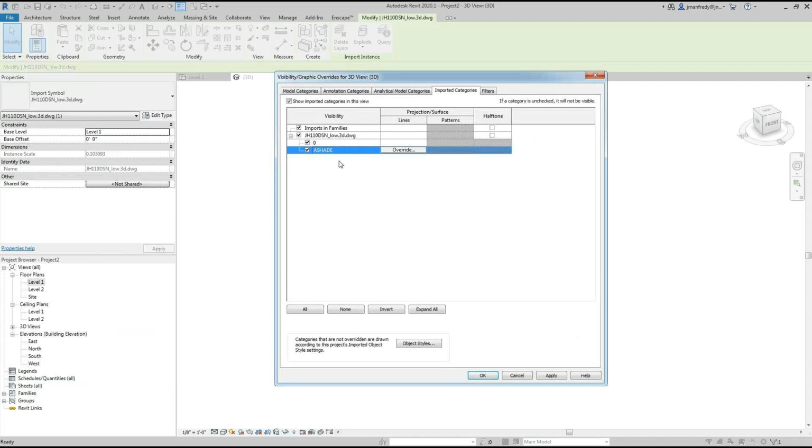These 2 happen to be AutoCAD layers that are brought in by default. In an ideal world, you want an AutoCAD file that has all the objects on a variety of different layers, so that in Revit, you can actually assign materials to those layers so they appear correct in your renderings.